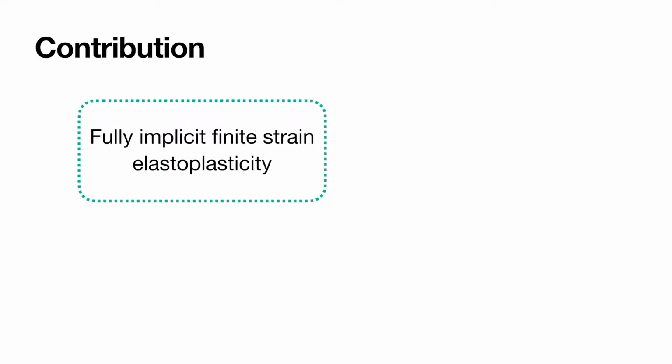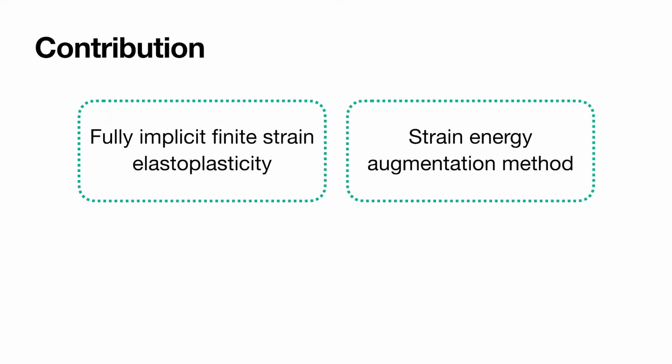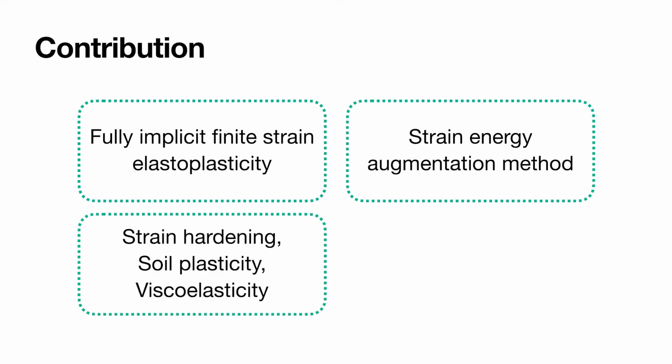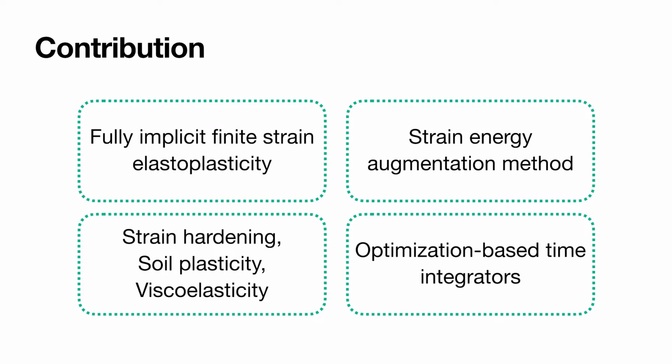Our contributions include an implicit internal force formulation for fully implicit finite strength elastoplasticity, a strain energy augmentation method that uses analytically integrable elastoplastic forces and symmetric force derivatives for von Mises plasticity, an extension of our model to support strain hardening, pressure-dependent soil plasticity, and rate-dependent viscoelasticity, and algorithms for incorporating our model in optimization-based time integrators with the material point method and finite element method.